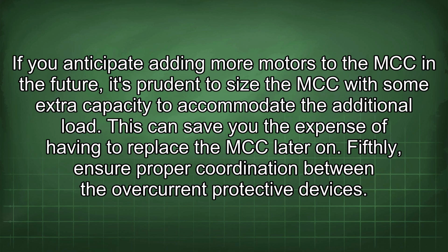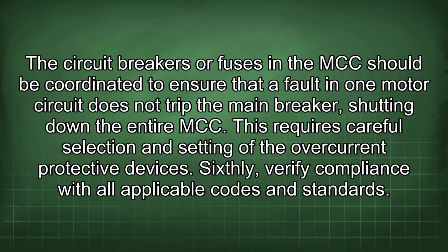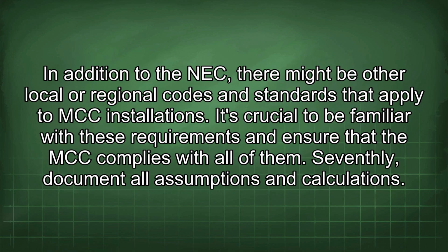Fifthly, ensure proper coordination between the overcurrent protective devices. The circuit breakers or fuses in the MCC should be coordinated to ensure that a fault in one motor circuit does not trip the main breaker, shutting down the entire MCC. This requires careful selection and setting of the overcurrent protective devices. Sixthly, verify compliance with all applicable codes and standards. In addition to the NEC, there might be other local or regional codes and standards that apply to MCC installations. It's crucial to be familiar with these requirements and ensure that the MCC complies with all of them.